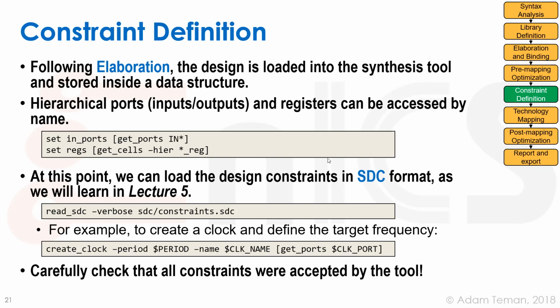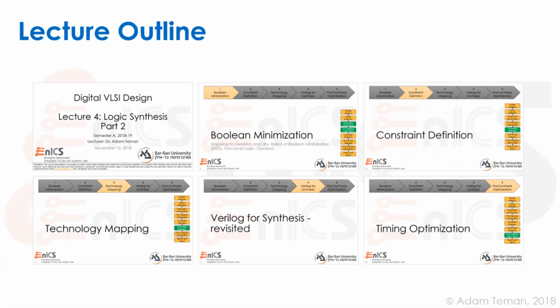Just one point: it's very important in the synthesis tool to carefully check that all the constraints were accepted, because if we made a mistake, we may not be constraining our design in the way we should have.